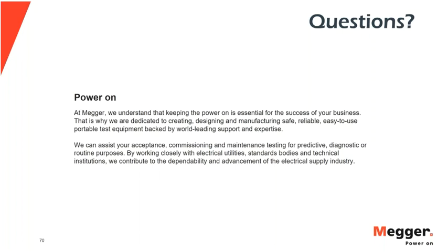Okay. Thank you, Diego. Next question, another one for Diego. Can we do SFRA analysis on all types of transformers, or is it limited for some typical type of transformers? One of the interesting things about this dielectric response, or I would say frequency response technique, because SFRA is not related to the dielectric directly, it's more related to the electromechanical condition of your transformer.